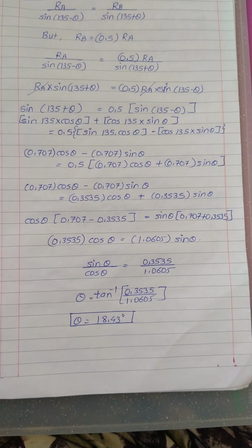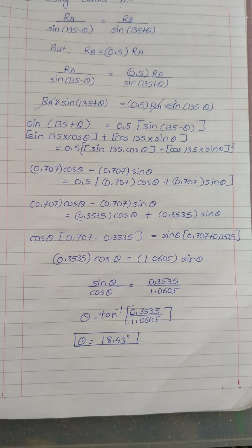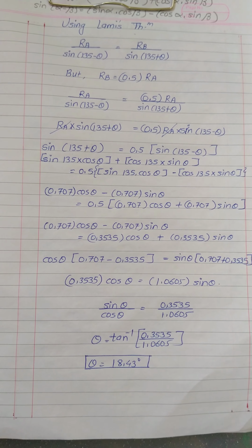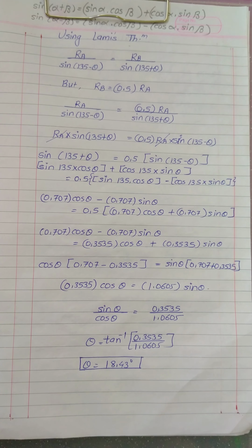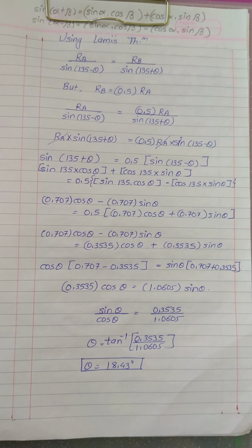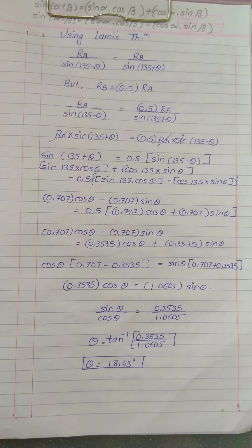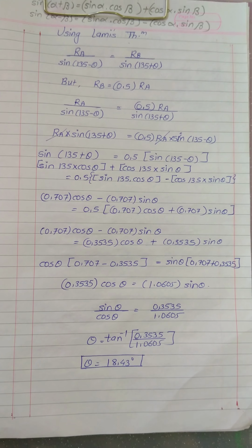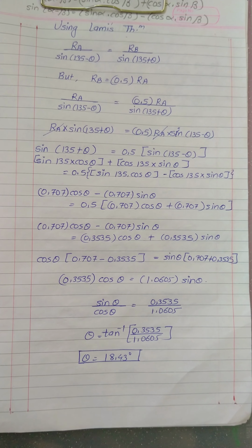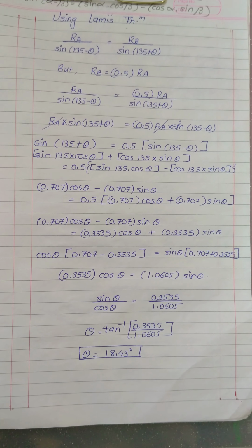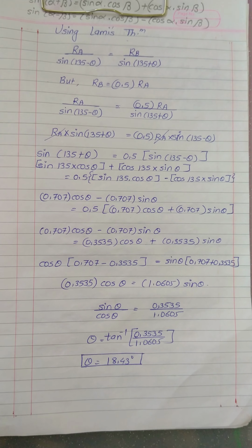Okay. So I hope you have understood numericals based on Lami's theorem, where we have applied Lami's theorem to a sphere resting in a trough or channel. You have to remember one thing: whenever a sphere is resting in a trough or channel, the forces acting at the contact points will be push in nature, because they will give a compressive type of force on that sphere.